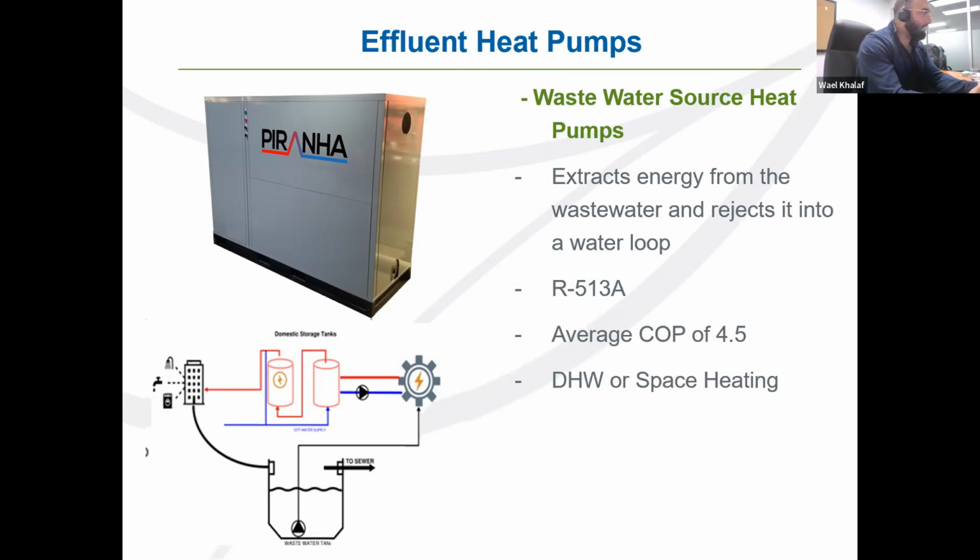If you look at using a gas-fired domestic hot water heater, you can notice that there's a big capacity of gas required in order to heat domestic hot water. But if you're able to use a heat pump for it, that's where it becomes really interesting to try to decarbonize a specific building. This is where we're seeing a lot of consultants adopt and look into this technology. Especially very recently, the CO2 machines are interesting because CO2 is so adequate for cold entering temperature and very high hot water temperature leaving the heat pump. So we are seeing a significant uptick in heat pump requests for almost any application possible.